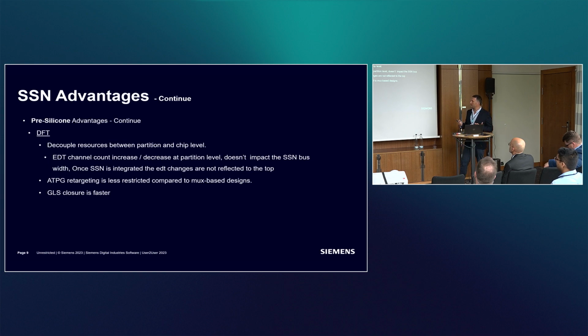So it's easier for the physical design to close 400 megahertz or 200 megahertz data, rather than what they had to do with everything coming out as global signals. The retarget was really an easy thing to do. And since everything is at the block level, the GLS was easier.